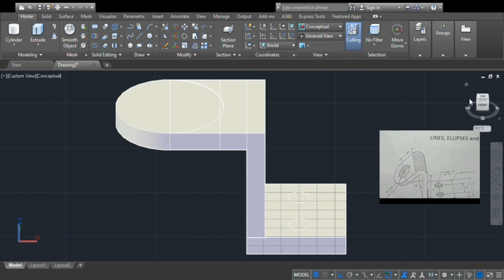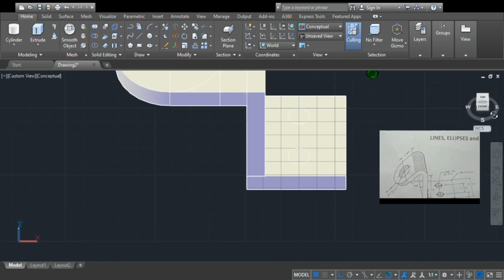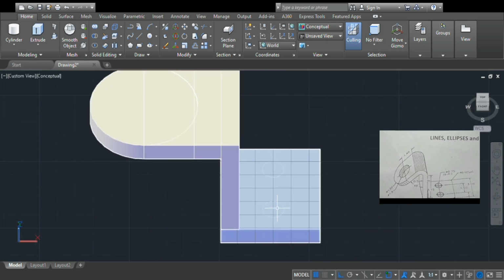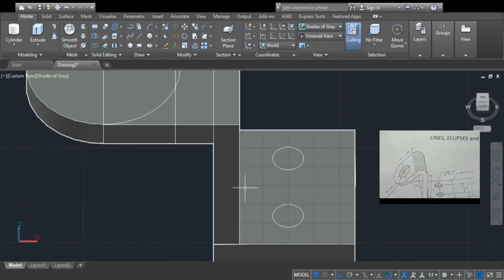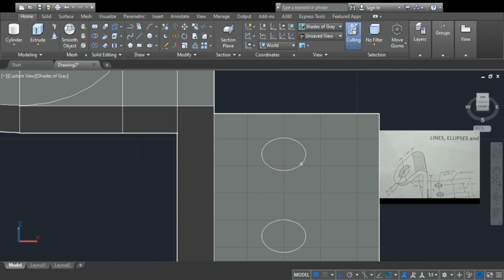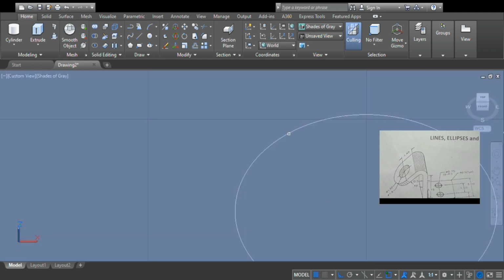Now all we have to do, I've just changed the color, is look at those initial circles I gave, put a hole in there, and also put another hole in the mid circle on top, then find a way to somehow bend the object at a 49-degree angle, because the angle is given in the example. Okay, so to remove the hole, like to trim down the hole from the circles, or extrude down the hole, or just cut it out anyhow, the best option to use is the subtract tool.